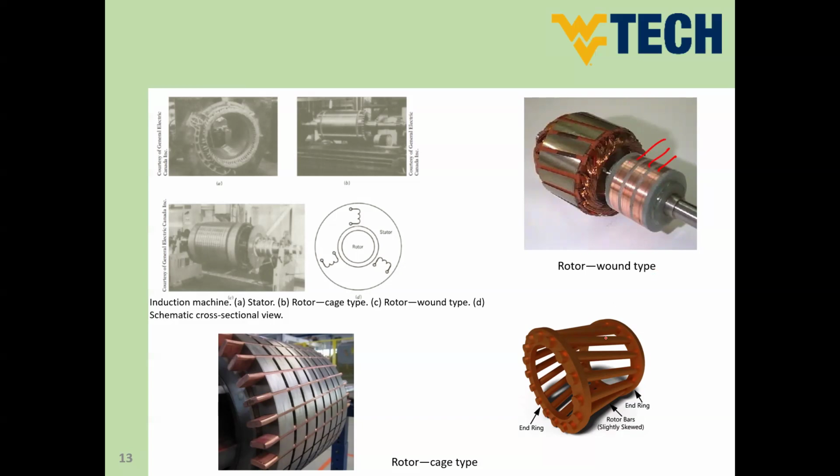And we have another well-known configuration called squirrel cage. The squirrel cage is used a lot compared to the wound rotor type, and we don't have any kind of windings. It's just some bars like that, or a cage like that, and this will act as a rotor winding, and this will also allow the induction motor to operate.